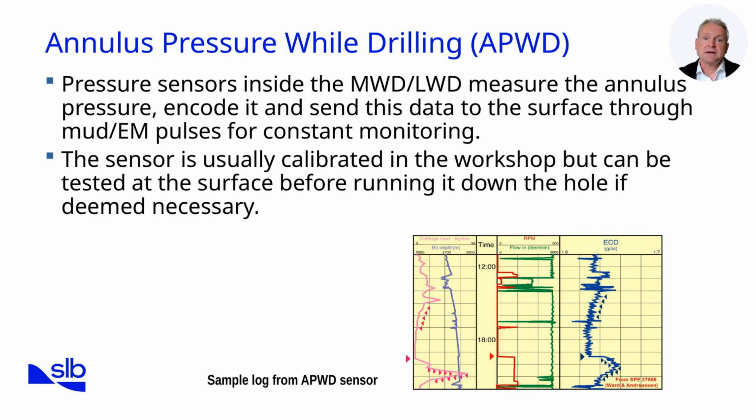The BHA in the hole is a motor assembly. What you can see is that in the slide sections, the ECD drops, but when the rotary is kicked in, the ECD spikes. This is because when sliding, the cuttings are settling out on the low side of the hole, which therefore is not part of the frictional losses that make up the ECD measurements. When the rotary is started, the cuttings become part of the fluid system, again heavily loading the hole and causing the spike in ECD.